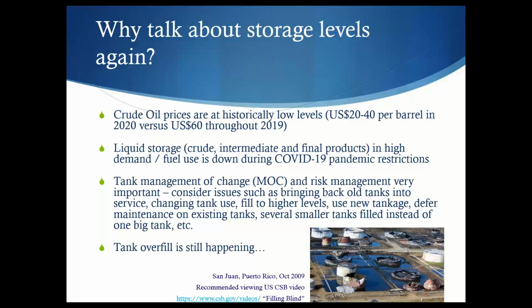The US Chemical Safety Board also came up with a number of findings around control failures. They had unreliable level control and monitoring systems that did not provide accurate and timely information for the operator to prevent filling. Failure-prone float and tape level gauges, unreliable level transmitters proved ineffectual, frequently out of service due to lightning damage, apparently.